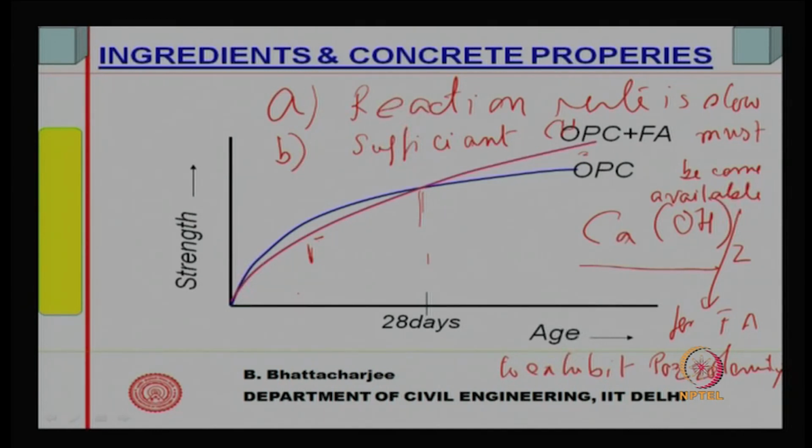So, this is the case with blended cement or fly ash addition. Whenever you add pozzolana addition, blended cement, of course, grinding can be more to compensate for this somewhat, but if you add fly ash in the mix and design it for the same 28 day strength, early strength is unlikely to be high, and demolding time may be more. So, one must keep this in mind, but this is not a problem, because you can always design for higher 28 day strength as well. But the point is, if you have the same 28 day strength, early strength is usually less when you have a mineral admixture like fly ash added into the system.